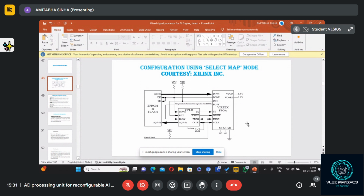You have to consult these manuals, where you have to understand the pin configurations. Timing diagrams are very important. Otherwise, there won't be any synchronization unless you understand at what time what is happening. Then you have to place the components, use a variable, connect all these signals and test it. Then your complete design exercise will be done.